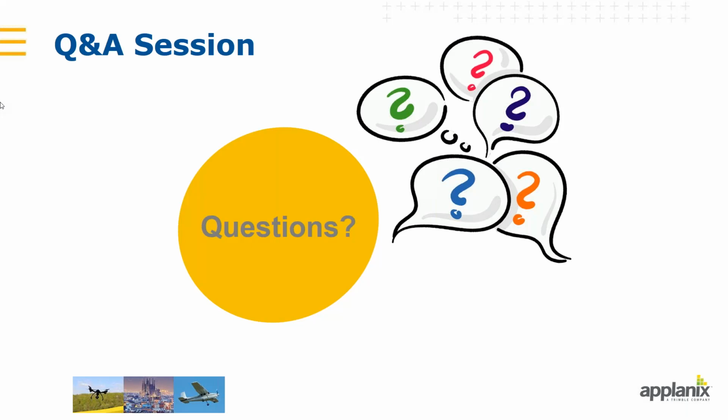Yeah. This question was specifically related to processing UAV data, but I think it makes no difference. Yeah, it's not. So the base station can be used for all of the various business lines, whether it's airborne, land, or UAV or marine, doesn't matter. As long as it's a base station and comes in a T02 file, which is a native format, or in a RINEX file format, and it has that 1 second data interval, you can put it into POSPac and run the processing without an issue.